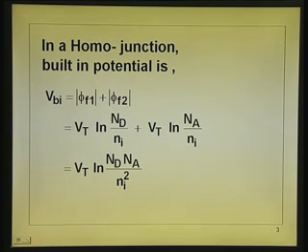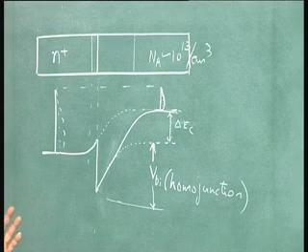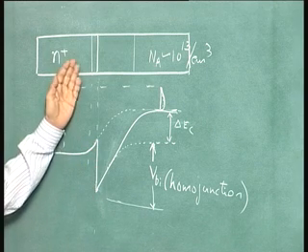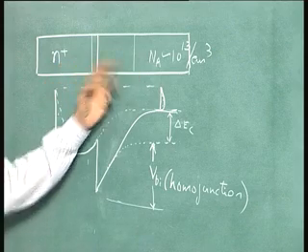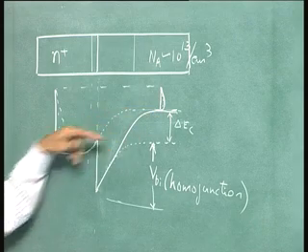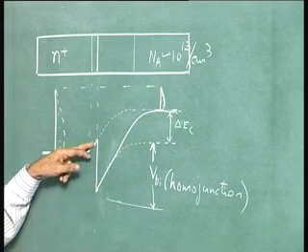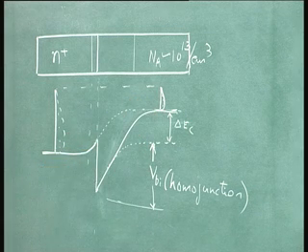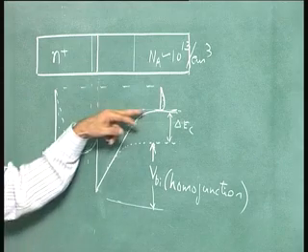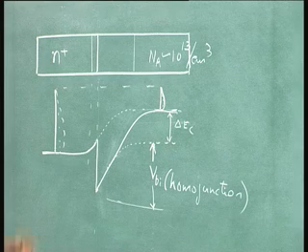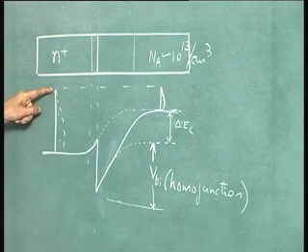Now, let me go back to this particular diagram which we have put in here with a bit more clarity. So, what happens here is, supposing this notch were not present, the Fermi level here is higher in any case. From here to here, the electron transfer would have taken place, and finally, a potential would have built up there. That is the built-in potential. Let us take the case where notch is not present. Then the built-in potential that you have got here is VBI, which is Vt logarithm of Nd Na by Ni squared, okay, and the built-in potential builds up till you can see the Fermi level is the same there.